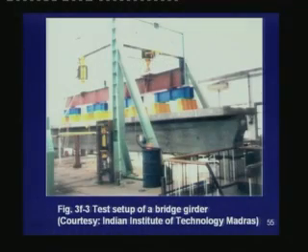This photograph shows a prestressed concrete beam being tested in a laboratory. The distributed load has been simulated by 8 point loads along the span of the beam. We see the reaction frame which supports the jacks. The jack is applying the load on this brown beam, from which it is transferring the load to these blue beams, and finally the blue beams are transferring the loads to the prestressed beam by these yellow load points.